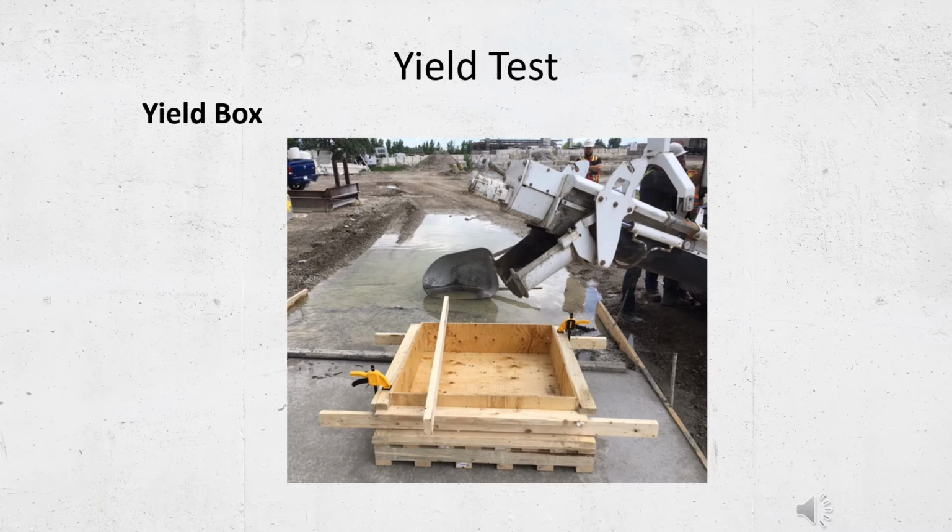In this example, we're proposing to build a quarter cubic meter box to fill with concrete. The dimensions will be 1 meter wide by 1 meter long by 0.25 meters deep and could be fabricated out of good quality spruce and plywood. It may be wise to make the form detachable from the base for unmolding and cleanup purposes following the test. It should also be sturdy enough to withstand multiple use without distortion in dimensions or volume.